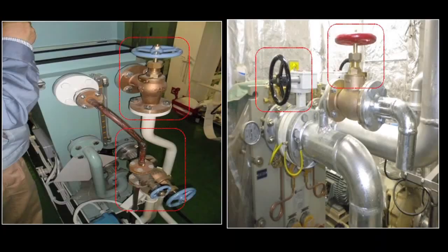1. Fill the level of cooling water more than medium level of FTU. 2. Open FTU inlet and outlet valve of fresh water. 3. Open HEU inlet and outlet valve of fresh water. 9. Setting up before operation. Prior to operating ECS, related systems, e.g. VMS, VRCS, etc., should be in normal operating condition.